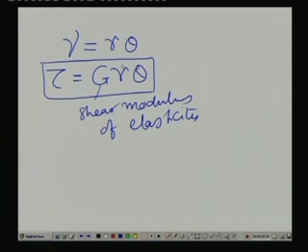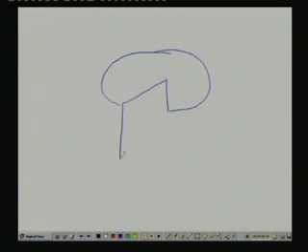Now, that means we can see that if this is constant, the shear stress variation is linear. In other words, we can see in a figure, if we consider the piece of cake sort of idea, then this is your shear stress variation coming like this. Okay. So, this variation is coming like this. This is a linear variation.